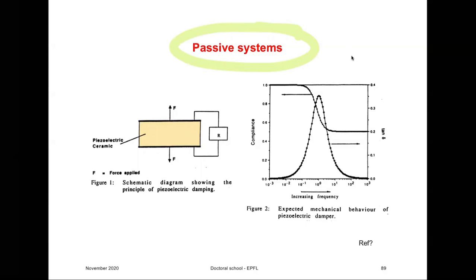Now, if you will have mechanical and then electrical energy, and if you can dissipate this electrical energy, that would then reduce vibrations. You make the material stiffer, and you can do it by using a piezoelectric shunt resistor across your piezoelectric elements.